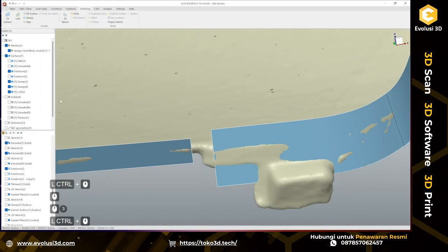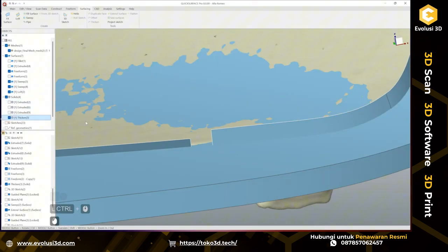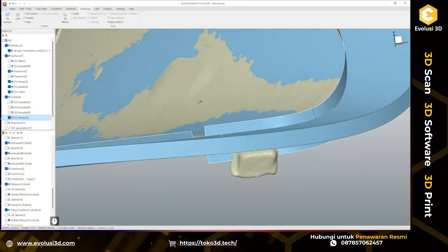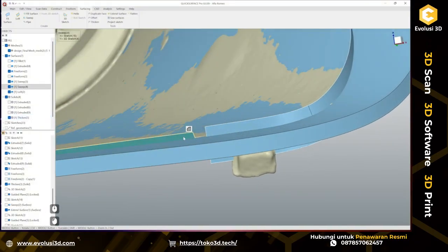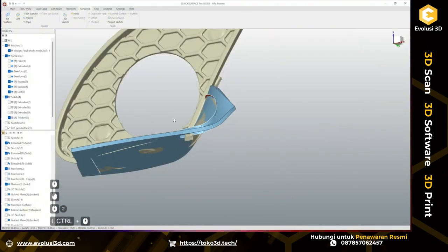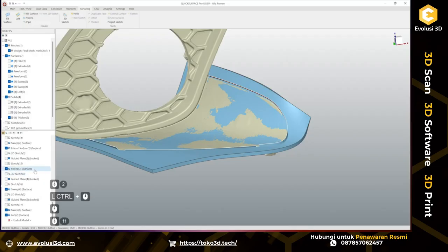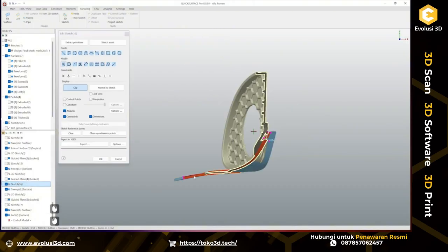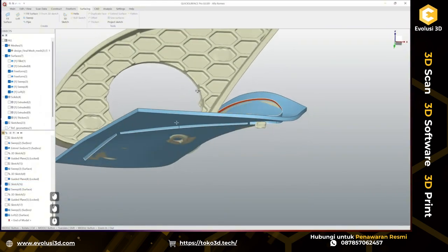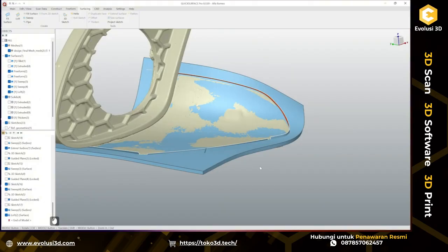Okay, so what we can do on this side, but before I'm continuing, I want to unhide my thickened surface to see if I have complete intersection everywhere, and I can see this sweep actually should be extended slightly. So in order to do that, let's edit our sketch and pull it slightly longer to the bottom side. Okay, now we're good to go.